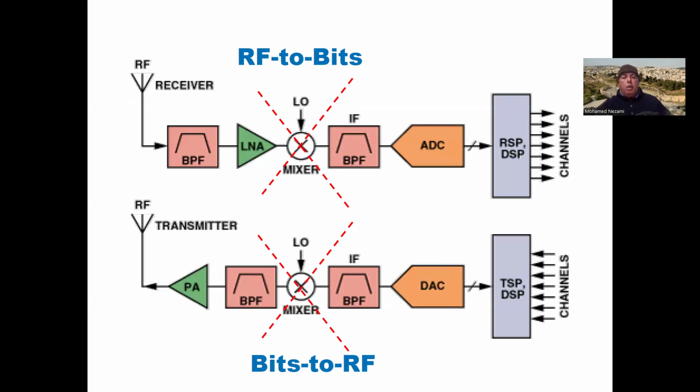Okay. All right, so let's go further. One of the feedbacks that I got from part one and part two is that a lot of people are still not seeing the picture of how you really directly sample an RF carrier, say at 28 gigahertz, using 10.8 gigasamples per second, for instance. To them, it seems like they still have the idea that, wait a minute, to sample a signal and recover it in the digital domain, you really have to sample at twice the frequency. And that's not true, really, because it is true for the information bandwidth, but not the carrier.